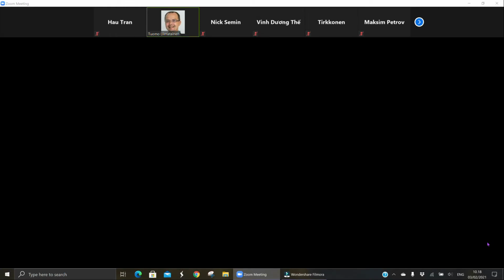And soldering is always an option, and the difference between welding and soldering is that in welding, the base material always melts, but in soldering, the base components do not melt. Only the material to be filled, the soldering material, will melt. And therefore, when the attached components do not melt, it will introduce less deformation and less residual stress than welding. But the downside is that the joint strength is, of course, a bit lower compared to welded, and